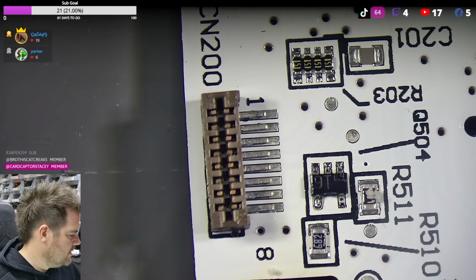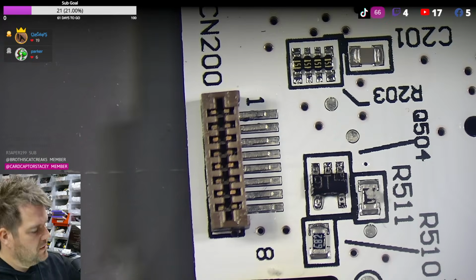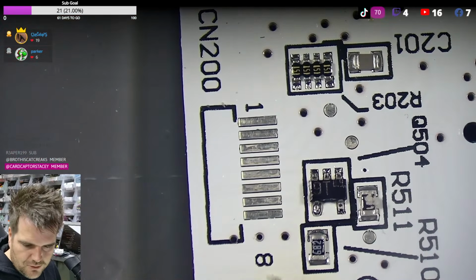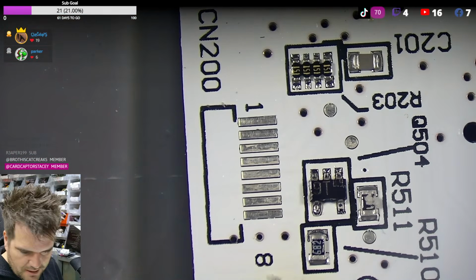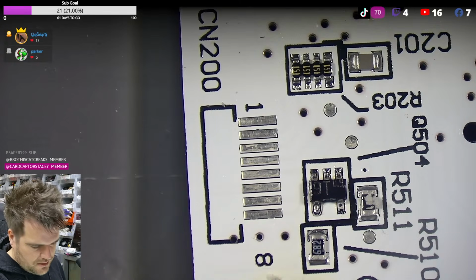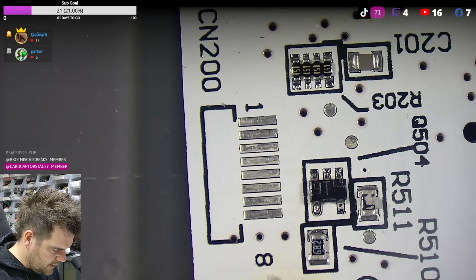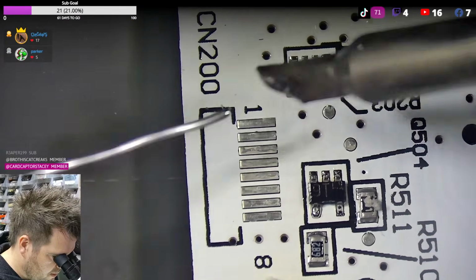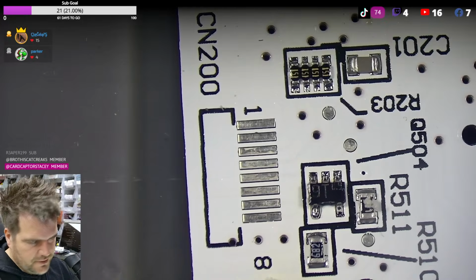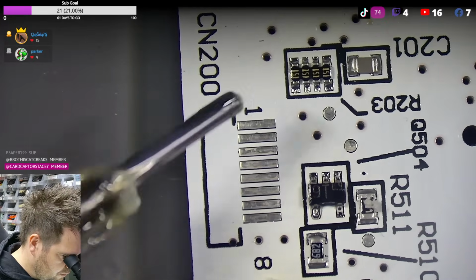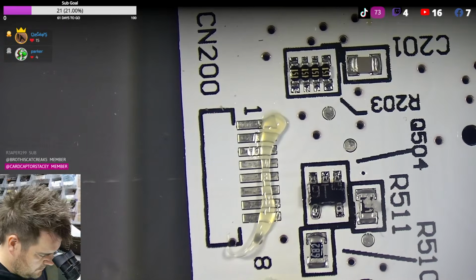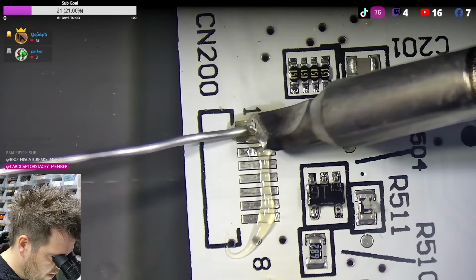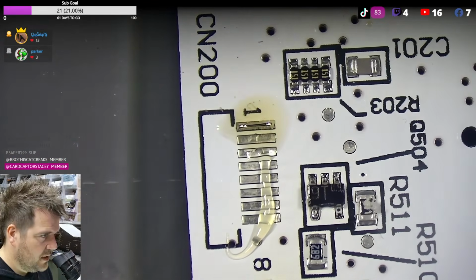This is the first time you guys will have seen me actually soldering with depth perception. This is something you don't see me doing, because I have to solder from a top-down camera with massive delay. We still manage. I'm going to put this fan on now as well. I keep saying I really need to get this fume extraction stuff sorted, otherwise I'll have really bad throat. So I'm just going to tin. I'm going to clean the tip of the iron first. Then I'm going to put flux on. And we'll probably need more of that. But I'm going to pre-tin just one pad. So try your best to just tin one pad, like so.